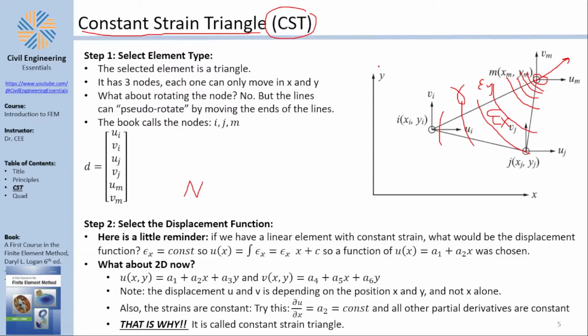We will be dealing with constant strain, meaning if you apply a force here, it produces a strain in x and y and gamma that is equal everywhere, which is an approximation, but it's the simplest of elements we can start with. Is there an element that deals with a change in the strain in the triangle? Yes, and it's called the LST, which stands for the linear strain triangle, something we don't know yet. Anyway, we have a constant strain triangle.